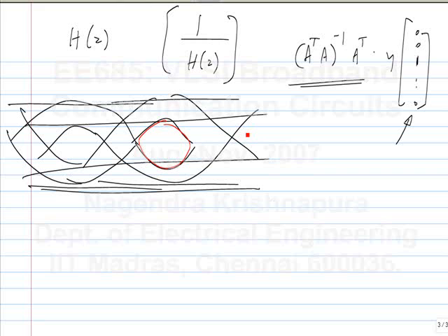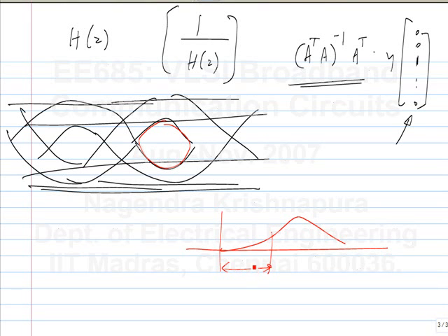No, I think, is it because of the starting transient? You have to plot the eye after the coefficients are stabilized, and you have to remove the initial transients of the filter, because if you don't do anything, it starts with a 0 value, right? There are 8 states in the filter, and they all start with 0. So if you look at the waveform in continuous time, it will start something like this. And if you include this part of the waveform in the eye diagram, it will look like some trace which is doing this, not this kind of thing. When you draw a crossing, the crossing comes in between on this side.